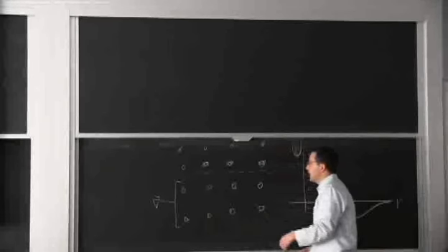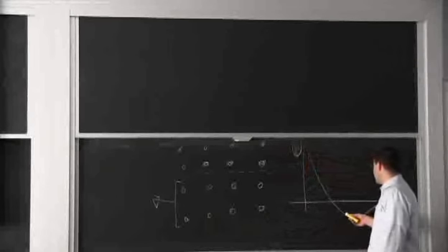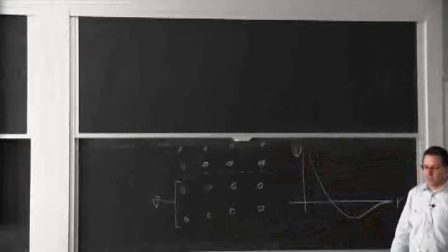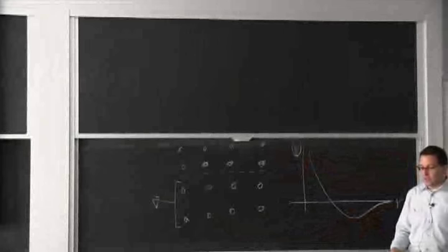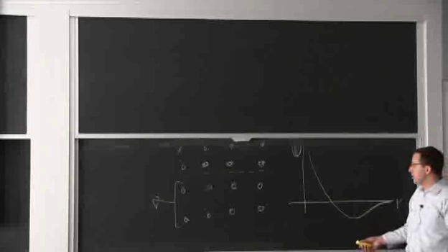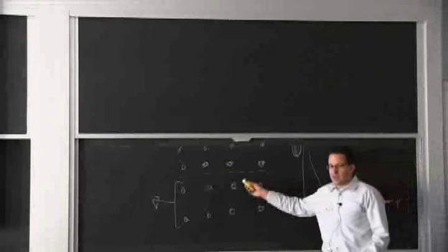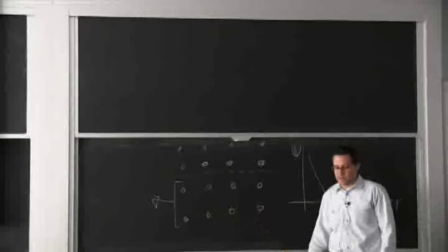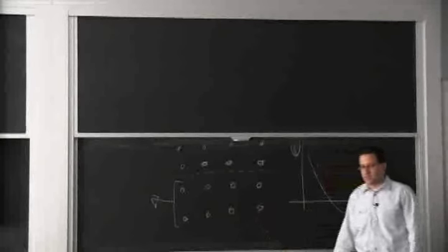So all together, the atoms will have to move from their equilibrium position. So what happens in reality is we have defects in the crystals that allow for just one step at a time to take place. And that requires less energy. We call those dislocations.